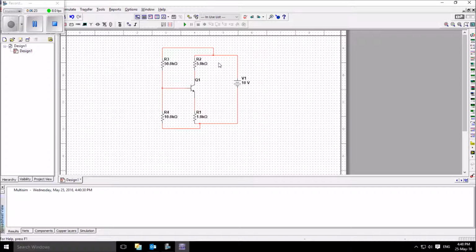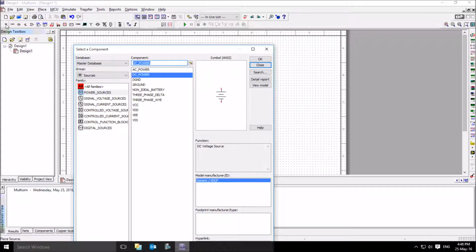But of course we needed some way of testing it, and to do that we can use the test instruments, which are on the right hand side here. Before I do that though, let me just say that all circuits must have a ground in them in order to work. And in this case we would normally put ground or 0 volts at the bottom end of the battery. That is the normal place to put it. So if I put 0 volts down here, that makes this 0, which makes the top of the battery 10 volts.